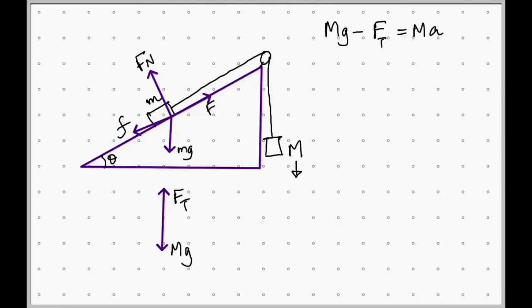So Ft. Now what is the net force along the x-axis? Remember, we have our x-axis along the plane and the y-axis perpendicular to it. So would it be Ft minus friction? Exactly. Ft minus friction is equal to m times a. And what is friction? Mu k. No, now that changes. So it's mu k times Fn.